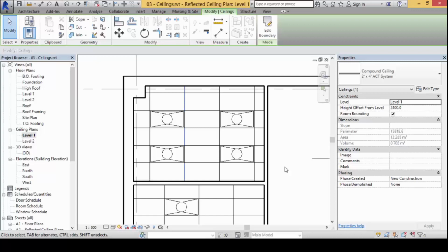A seasoned eye looking at your ceiling plan would know your degree of thought and planning put to it. Did you plan this before you think about the furniture layout, or did you plan this after the furniture layout has been established? Because once you start having the cabinets here, the shelvings here, and so on already, do you think it's still centralized?